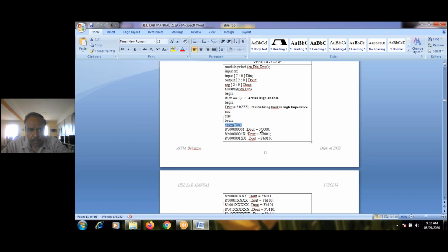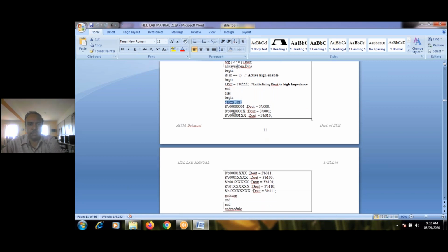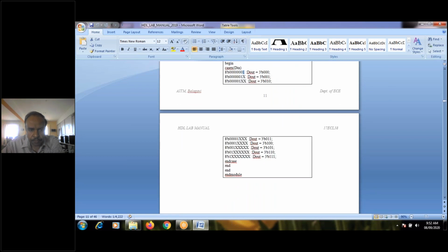Okay. So say 8'b00000001. Okay. So this is your D naught, right? If it is 1, it will give 000. Clear? Say this is the highest priority. Your D7, or say it's din of 7. If it is 1 means it will not check for any other lower priority bits. Don't care. Directly it will give you the output as 111.